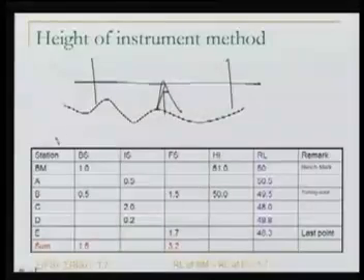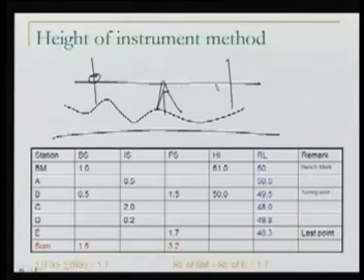Using this horizontal line of sight for a small area, we can say horizontal, we determine the readings RA and RB. Then if I know the RL of this particular point, I can compute the RL of this point. So this is what we have understood. But how actually we implement this thing in field? This is important. So this is what we are going to do now.